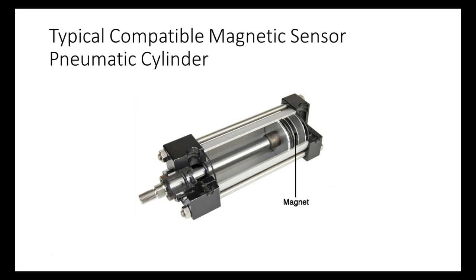We've got some magnetic switches over there. If you take fluid power, hopefully, when Allison teaches it, she shows them those things. And you strap them on the side of the cylinder and you put a pneumatic hose into it. And when you put it there, it closes the valve or opens the valve to let the pneumatics go through. So that would be a reed switch. That'd be an example of a reed switch, but it's controlling another power source except for the size of electricity.